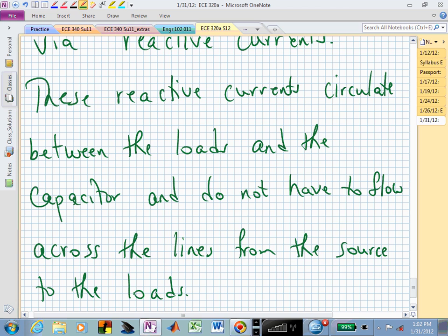Now if you stuck a resistor in there, which you're doing by these transmission lines, you now have to push 144 amps instead of 184 across that resistor, which is your transmission line, and you're going to have much less loss, and you could compute the apparent power from both particular configurations. And now it's the difference between V sub G, 500 times 184, and V sub G times 144. Am I using the right numbers? It's buried. But yes, you're asking for less power now since you've corrected with those capacitors. Obviously, you would have to buy those capacitor banks and flip those into play so that you could now be able to save some on your power bill or on your energy bill.